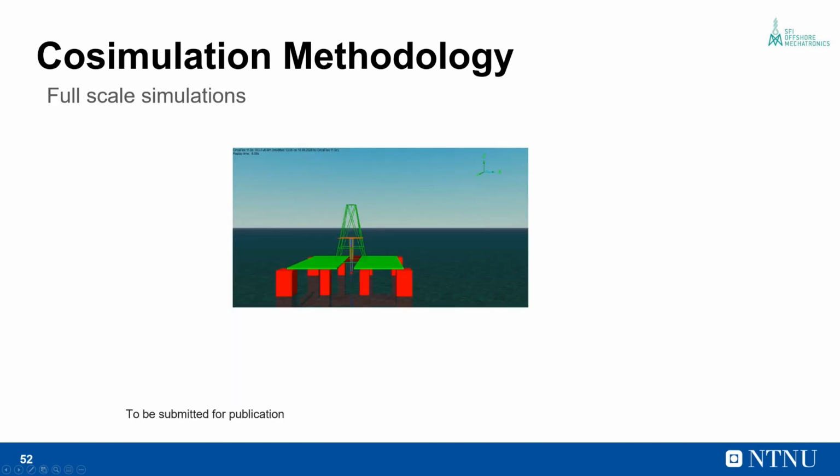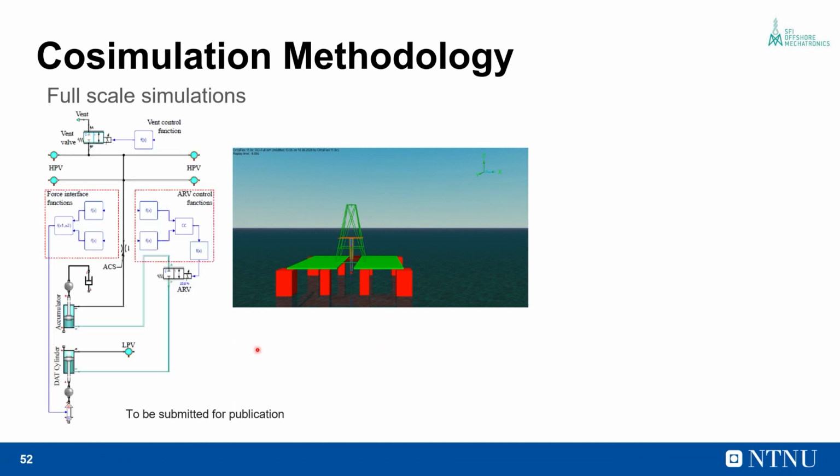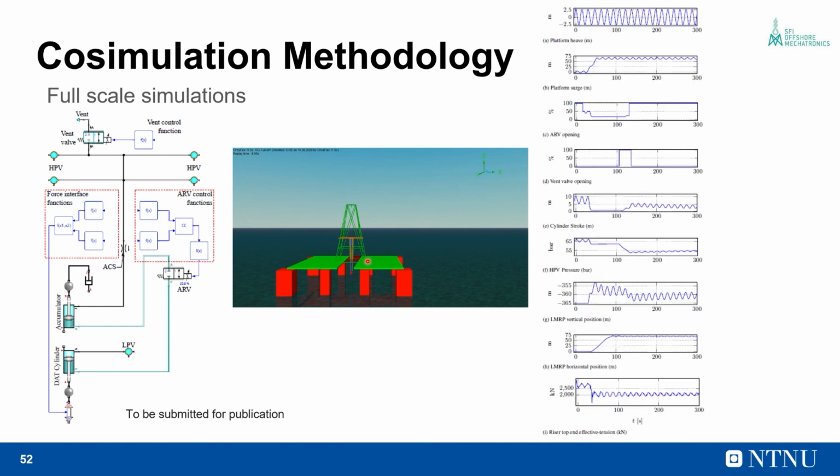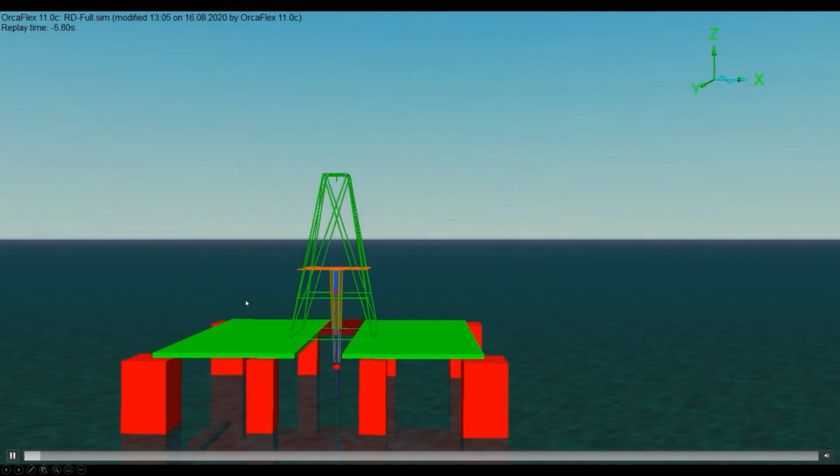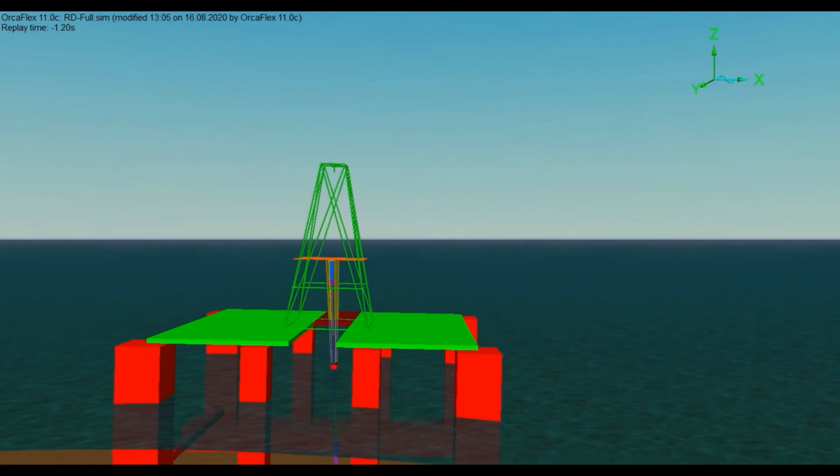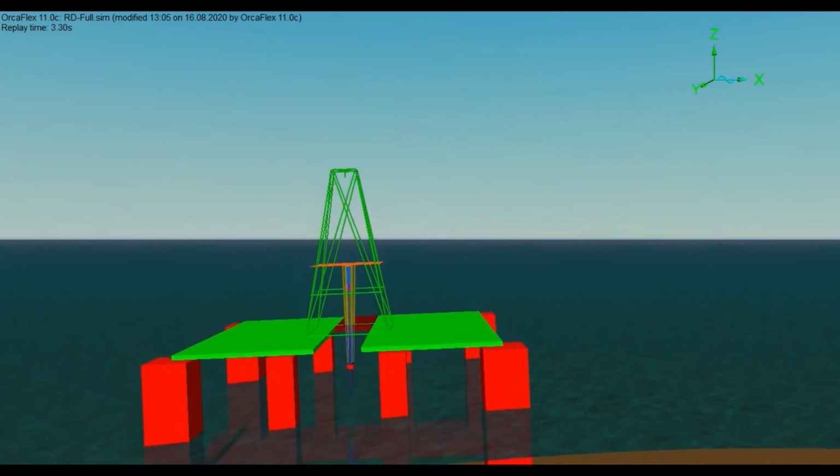Having successfully simulated the simplified system, we extend the methodology to a full-scale system where we model the entire riser tension system in Simulation X, and we model the semi-sub drilling platform along with the riser in Orcaflex, and we present the simulation results. Let's have a look at the simulation. So initially the riser is in the connected condition and the platform is responding to the waves.